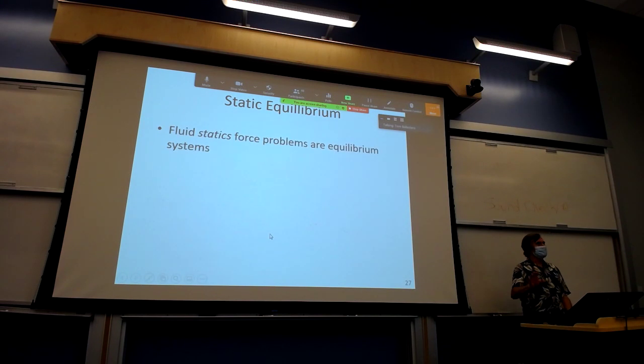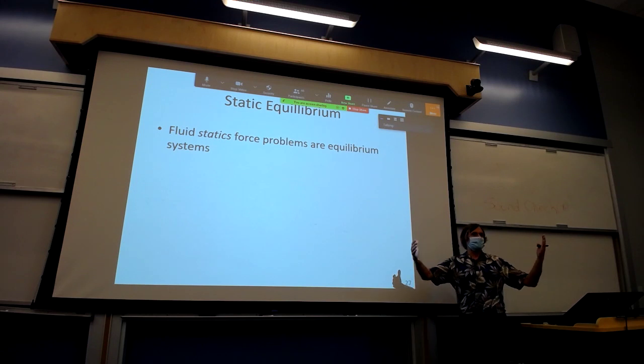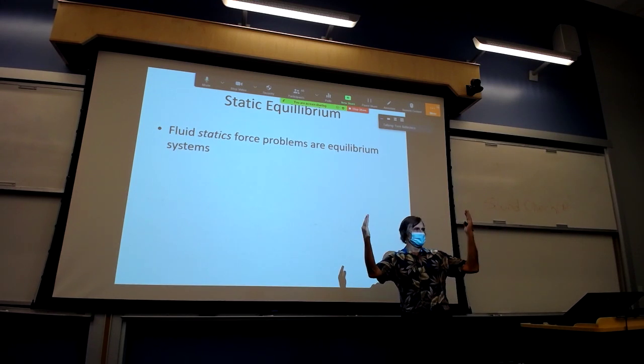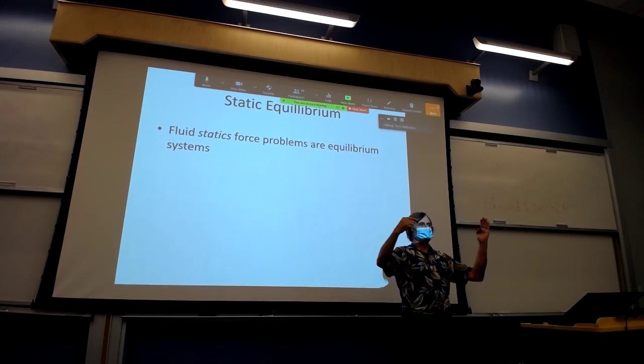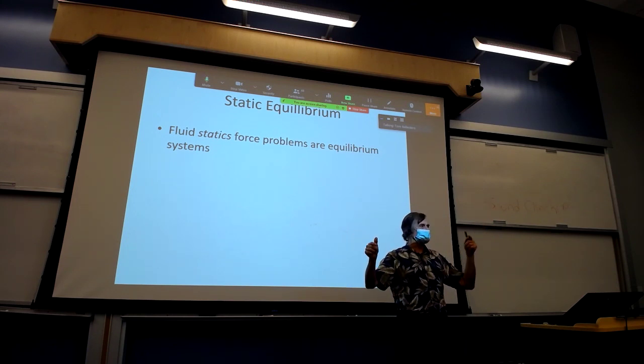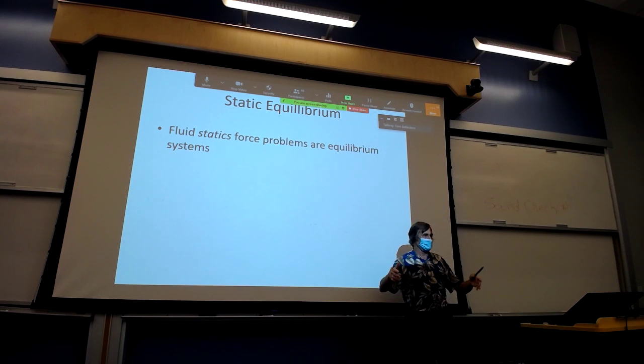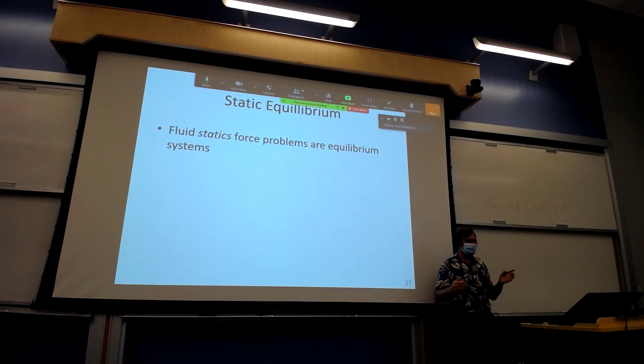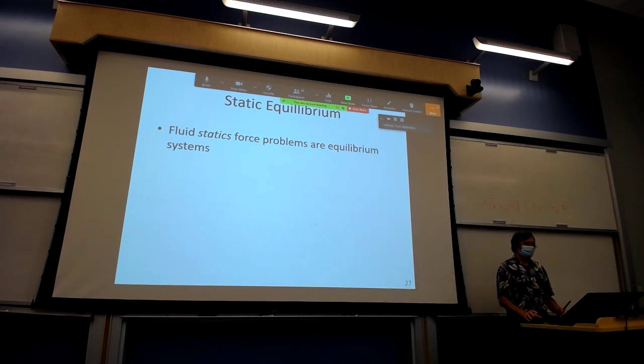So, we can work problems in a static equilibrium. When I talked about the rails, we said that the force of 98,000 newtons was being offset by a left rail force and a right rail force. And if you had an equal distribution of the forces, R_L and R_R would be the same. That's a force equilibrium.